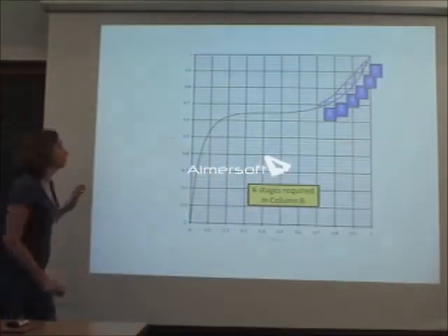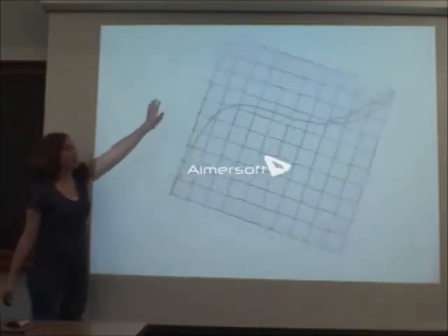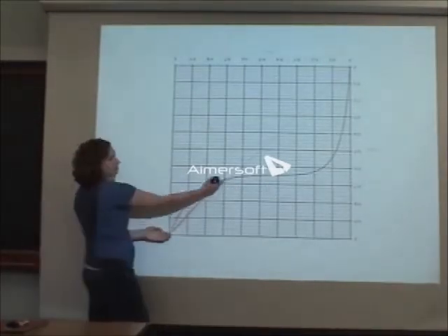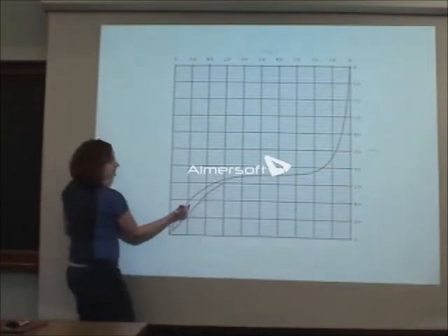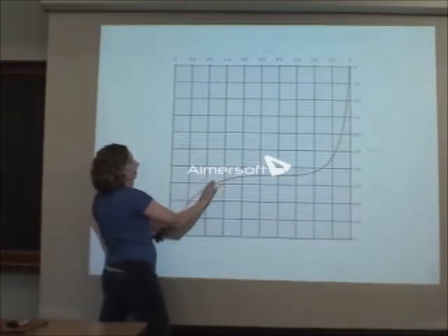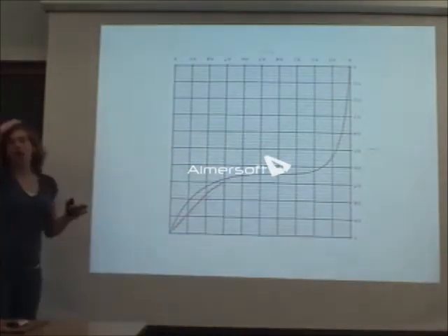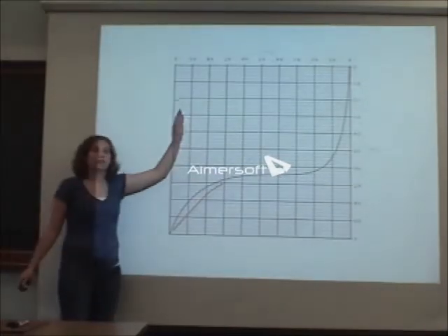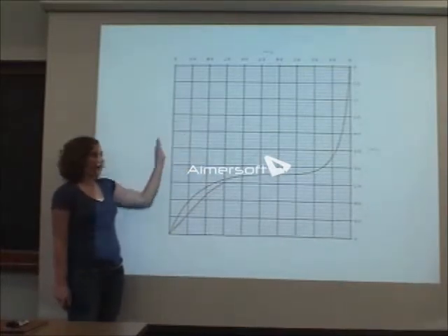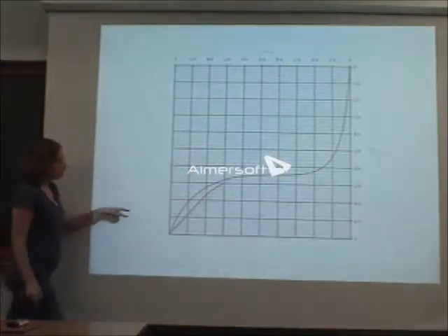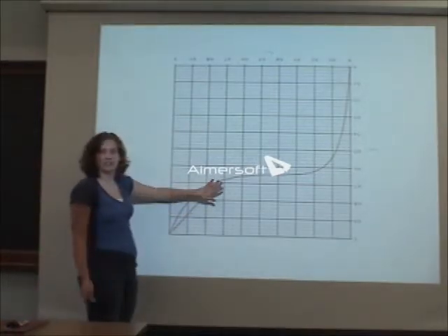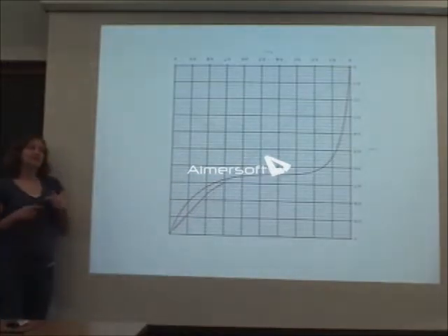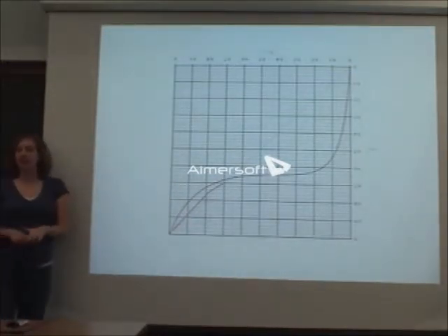And you know why that is? Because if I take this map and I flip it around, when we're in this area, this looks more like our normal equilibrium line, right? We generally deal with this here, and then we have our equilibrium curve being above our y equals x, right? And the reason we do that is because we put our most volatile component as our axes on these graphs. But when we go past the azeotrope, what is the most volatile component in the system actually changes.